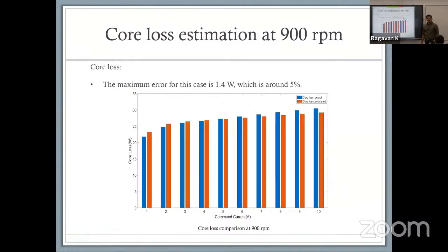What that told us is that using methods like the Steinmetz equation, which is a well-established method, the equations are not new, and you might have seen them before. So it's a standard equation, but using them in your behavioral model allows you to extend the capabilities. The reason why I thought this was particularly useful is because this cut down our simulation time from a few hours to a few minutes. And that was a huge difference for us, especially as we were changing. We started modifying the geometry because that was the next step I told you we were starting to do.